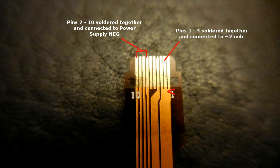Then on the opposite side, pins 7 to 10, you're going to solder all 4 of those together. Each one of those represents one set of 8 LEDs. Number 10 connects to the first set of 8 LEDs closest to where the ribbon cable connects to the LED strip. And then the next one down would be number 9, and then the next one after that would be number 8, and then number 7 would be the very end of the LED strip where the cable is not connected. So solder all of those points together like you see in this image right here.